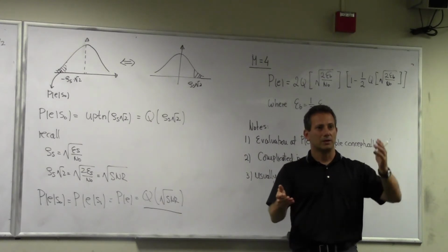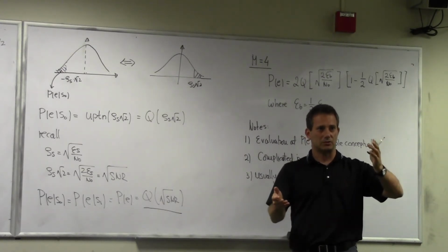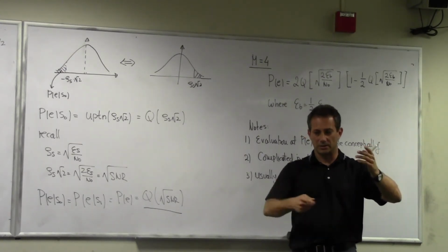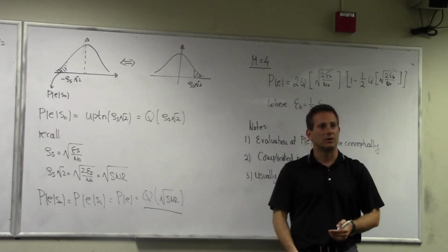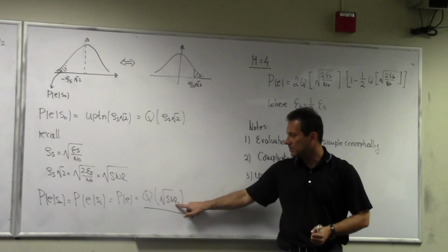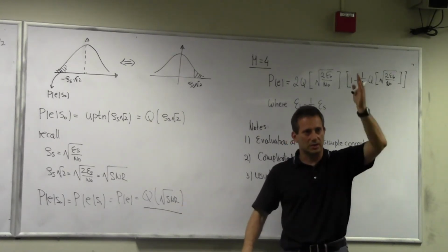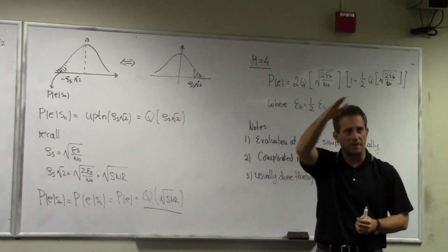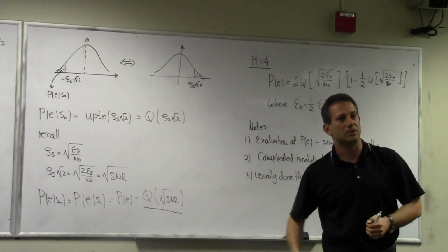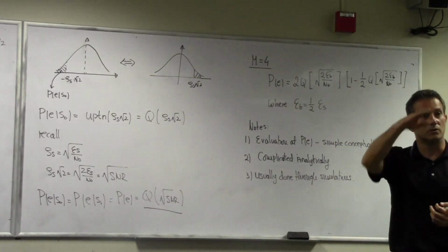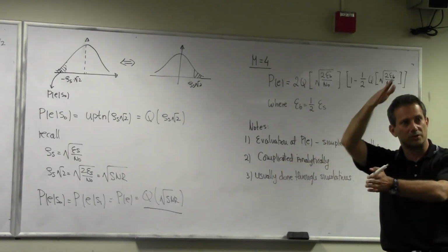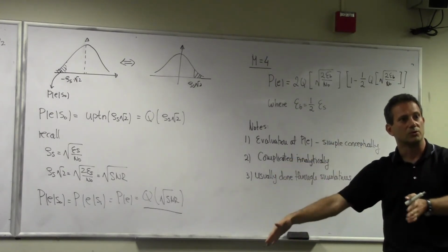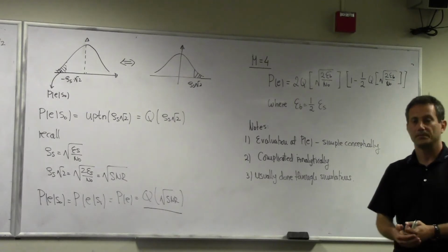In one log plot, we have dBs on the x scale and a log scale on the y-axis, right? Because then they become almost linear. Polynomial, almost linear. They don't become exactly linear, but for high signal to noise ratios they end up being almost straight, like your waterfall curves, right?